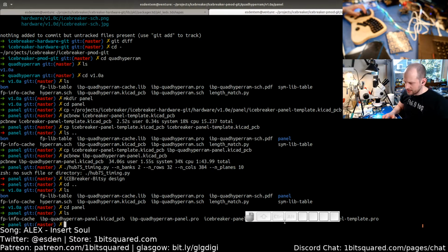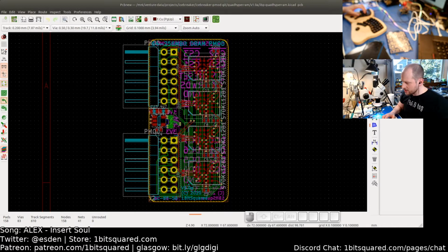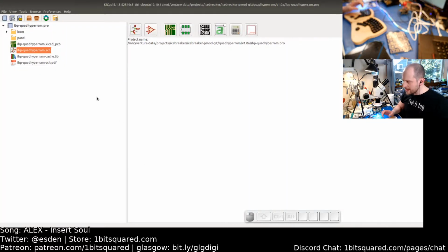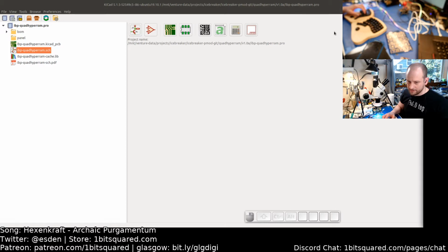And all the panelization is being done not in a full KiCad start. KiCad, usually when you start it, you get this window, which is like a central console startup. You start all the other applications that KiCad is made out of here. But the schematic editor and board editor can be started on their own, individually, outside of this launcher.